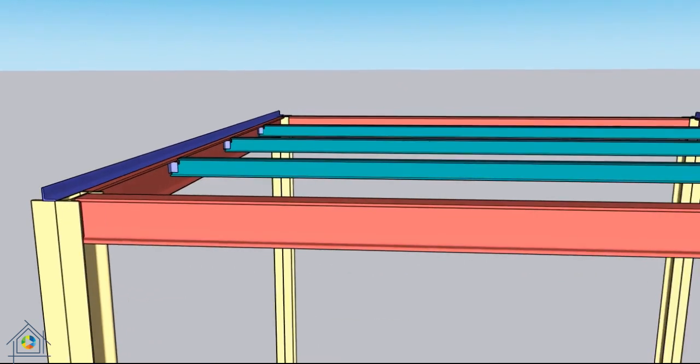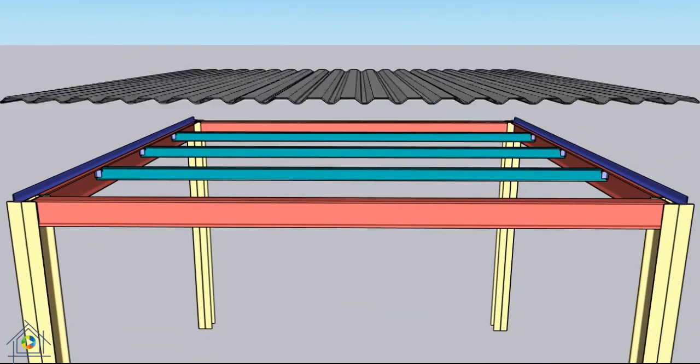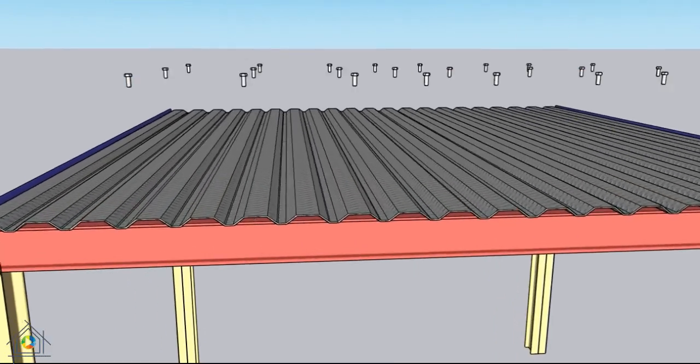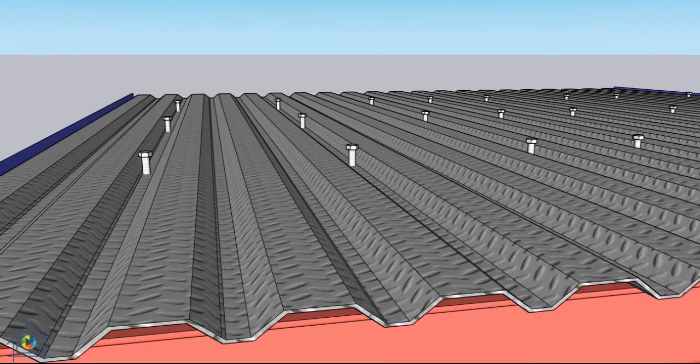The galvanized roof covering is called steel deck. Then the steel deck sheet is implemented between the two angles and on the beams. For proper connection of the steel deck sheet to the beams and also for uniform behavior of concrete and steel components, steel studs with appropriate diameters and distances are used with weld.